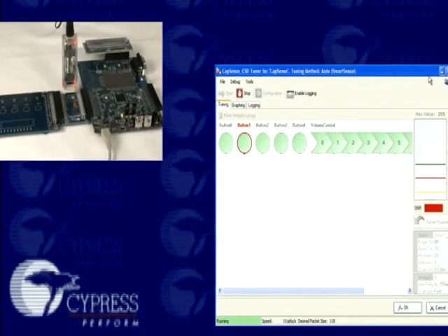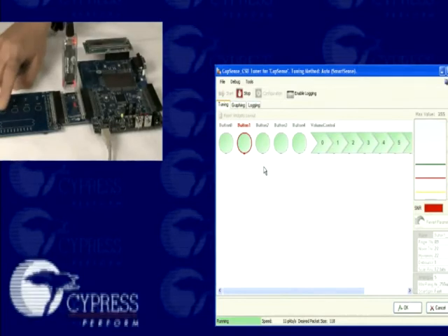And here I selected button number 1 so that I can specifically observe all the parameters and the performance spec of this element. So you can see when my finger is on button 1, and then on the right side you can see the SNR rate and the finger threshold, noise threshold, etc. And the reason all those parameters on the right side are grayed out is because the smart sensing algorithm is enabled in this example project. So over 10 parameters here are automatically optimized so that we can achieve the best performance.